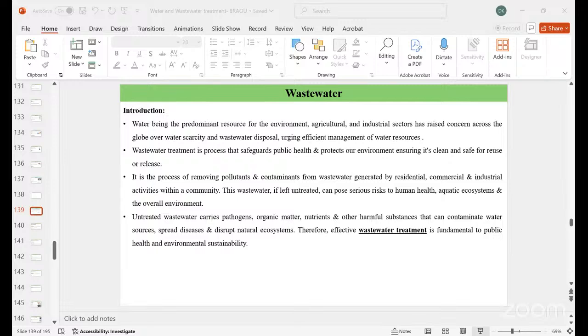Next is the key metabolic process, which majorly involves the removal of organic matter by the microorganisms through a variety of biochemical pathways such as catabolism and anabolism. Catabolism is the degradative process where complex organic molecules are broken down into simpler ones, releasing energy. Anabolism is the biosynthetic process where simpler molecules are used to build complex cellular components, leading to microbial growth and biomass production.